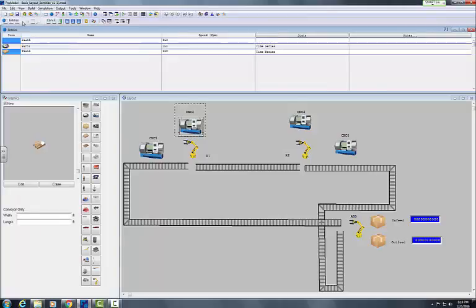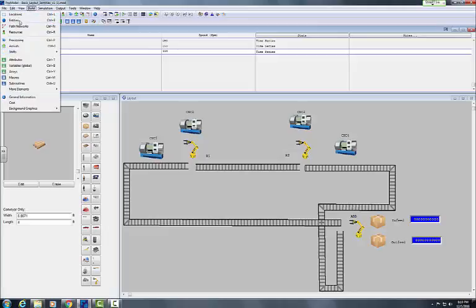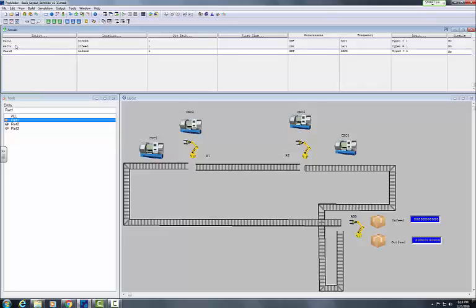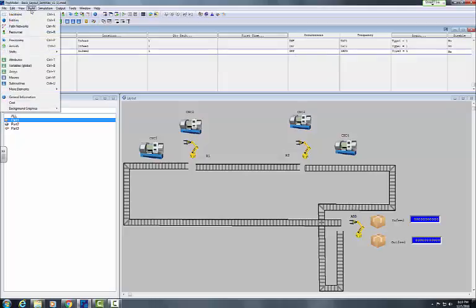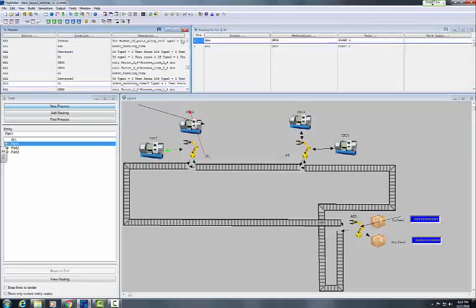Then you go to the entities, define as many number of entities as you want the test bed to produce or operate upon. After locations, after entities, you would go to arrivals. Arrivals is where you say the entities come at so and so time and so frequency, and then finally you would build up the processing table.